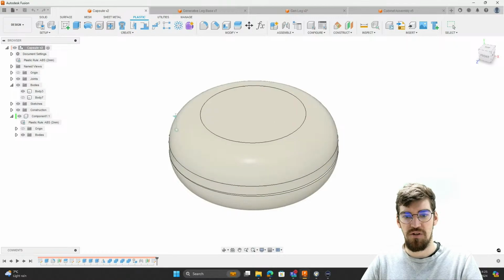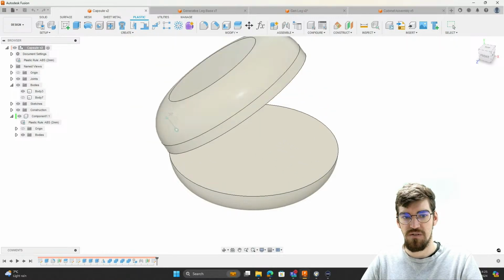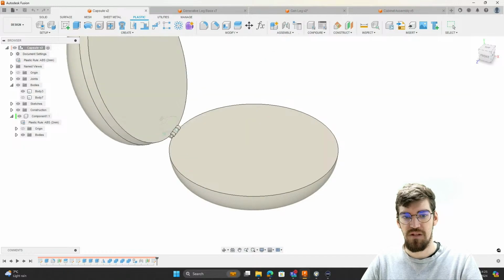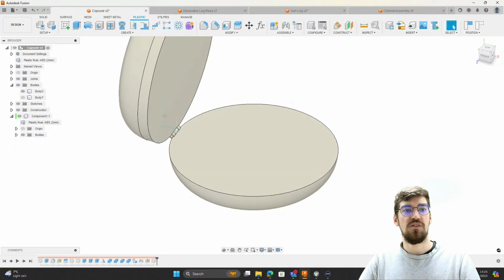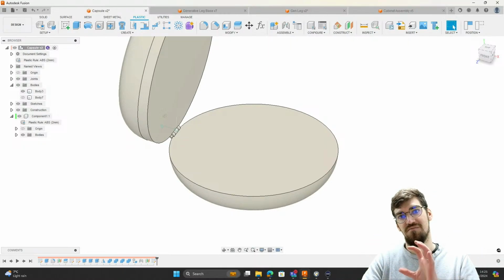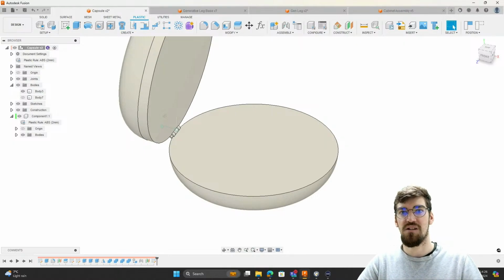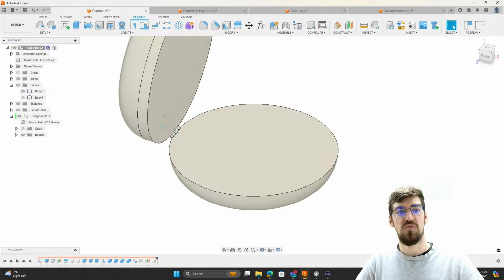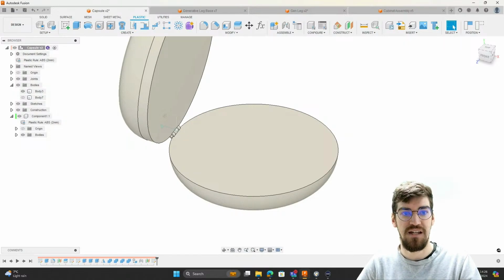I've got a second component just to allow some motion between these two to create this nice joint over here. Now against each of those two components, I can start to add a bit more detailing. So I've got the main shell of the component, I've got the main estimated external geometry in place already. I want to then assign a rule set to it, which I've gone in and assigned to more ABS. I can then start to use some of the modification tools and creation tools to start bringing out all of that information, all of that data.